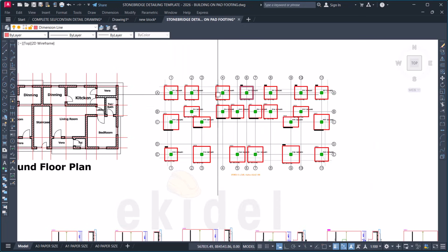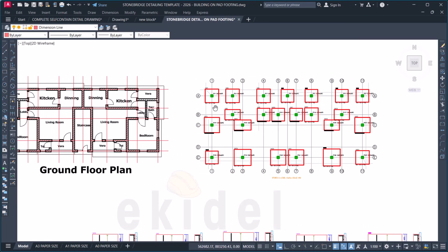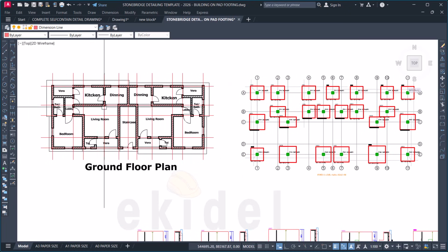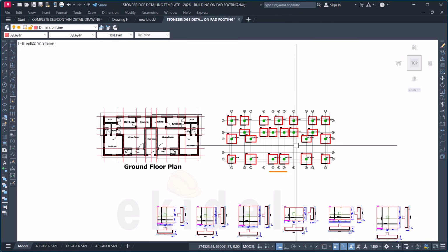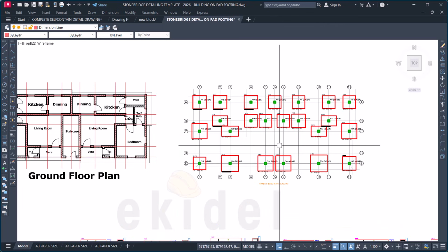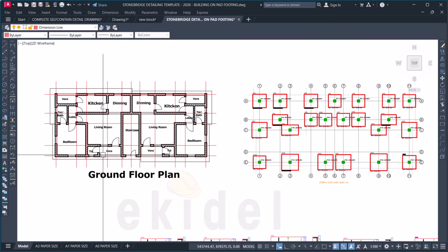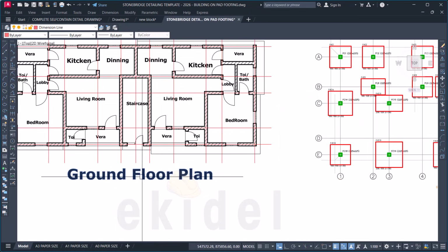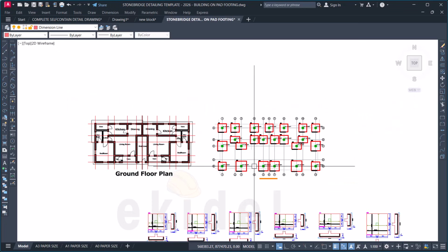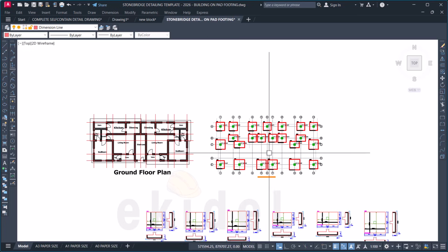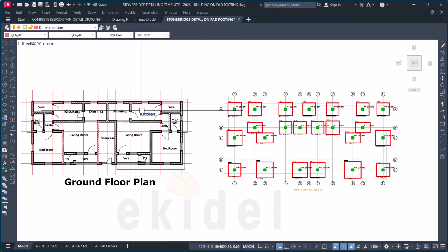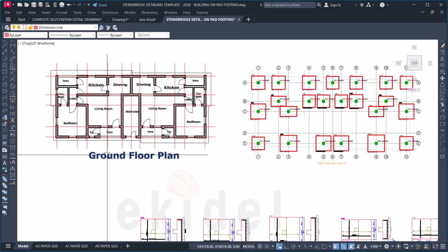So since the purpose is for digging of the foundation trenches, and we want to work with the foundation block walls, or the block walls that will start from the foundation, that is what we want to dig trenches for. So you have to work with the ground floor plan, because that is the floor plan that has interface with the soil directly. Other plans, for example first floor, second floor, have interface with the floors above. So we will be working with the ground floor plan.